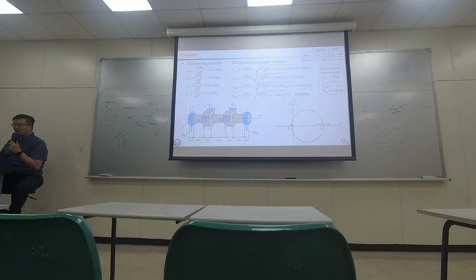And this is how I like to remind myself what the K values are for different stresses: static normal, static shear, dynamic normal, dynamic shear. If I write it down next to me when I solve the problem, I can easily grab the right K value, so I won't make mistakes.